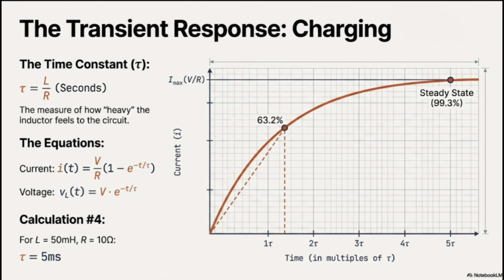As I mentioned, the time it takes for an inductor to get charged is 5 tau, just like the capacitor. But the tau, or time constant, follows another formula: tau equals L divided by R. L is the inductance of your inductor, and R is the resistance that your inductor sees while there are no sources. Most of the time, when you only have one RL, it is not that hard. But when you have a combination of resistance, inductor and, in the most challenging case, a capacitor, which we call an RLC circuit, it becomes very important. So at this point we just assume that tau equals L over R.